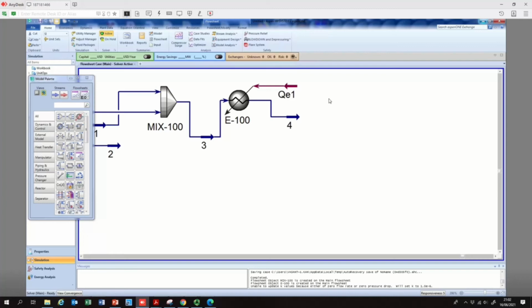It's very funny in Aspen HYSYS, you cannot take two streams and then add a CSTR and then maintain the temperature inside the CSTR. No, if you're performing some reaction, say at 800 degrees centigrade, you have to make sure the stream which enters that particular unit operation is at 800 degrees centigrade. That's how Aspen HYSYS works.